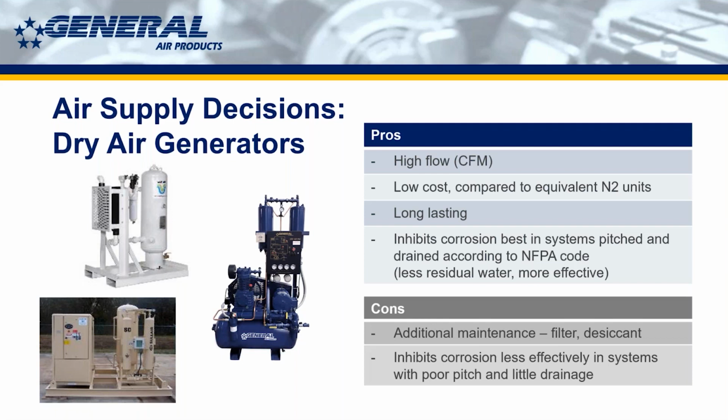On the business end of those tanks was a tube going into where the shells come out. This whole row of tanks had this tube going into them, and there was a dry air generator hooked up to them. As the dry air runs and goes inside, it keeps corrosion from forming inside the barrel of the tank, and also inside of the tank where all the electrical equipment is. It's reducing the moisture in the air. It's keeping the air very dry so the corrosion can't take place.